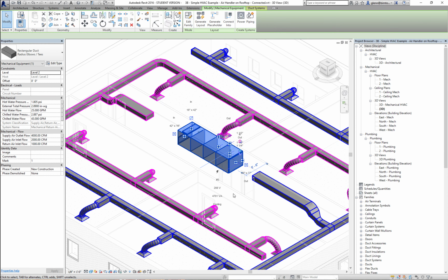If you choose an air handler like this, you'll notice that it has certain connections available to it. There's the supply connection here, the supply connection here, and the input for the return air up on the top. And when you see connections that look like this, what's actually happening is it's offering you a little handle to let you pull something out, a piece of pipe that is the same size as the connection.